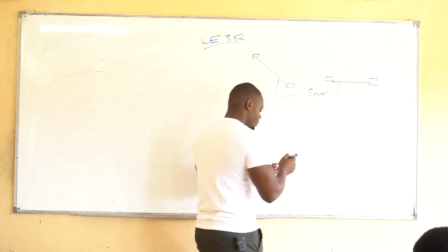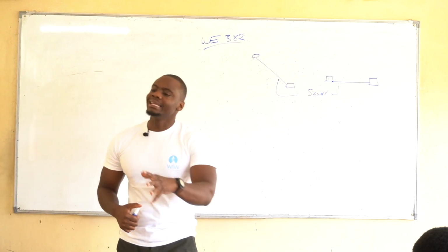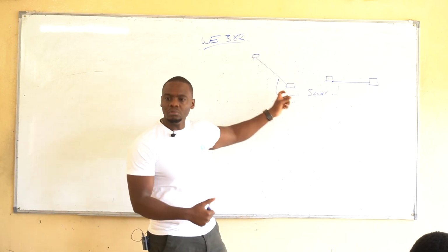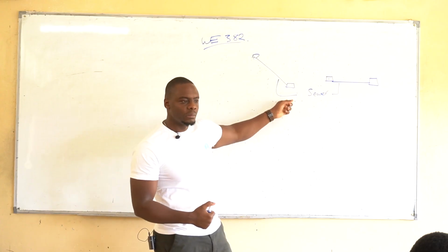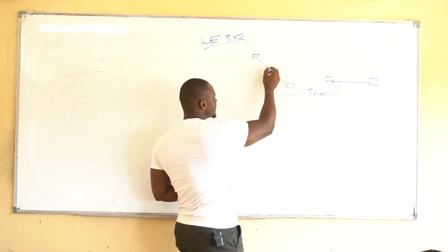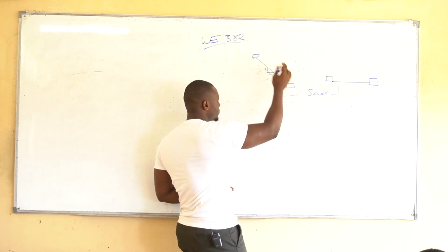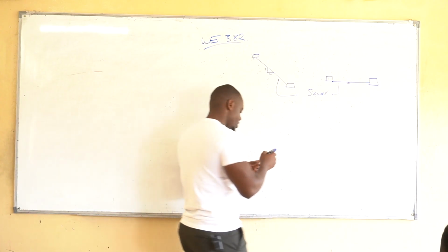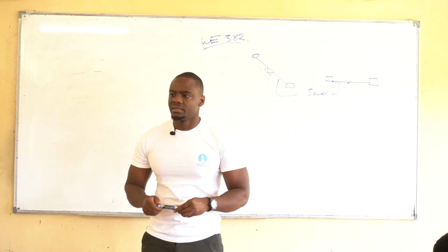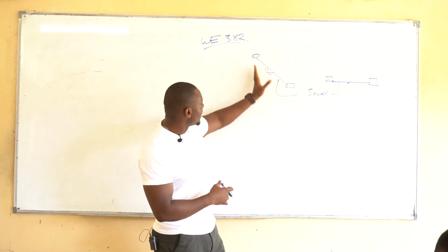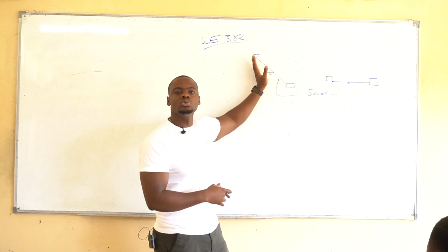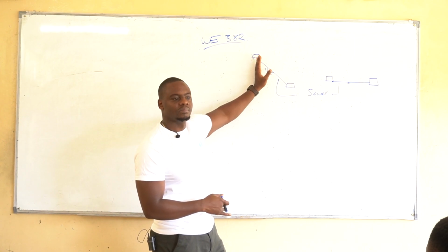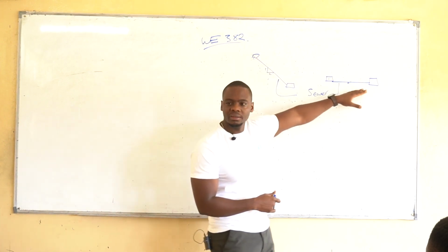And this is coming from what we call the self-cleansing velocity. There's the rate at which you want your fecal waste to move in that format. But then you cannot just guess the gradient. You have to calculate it. So we said if you just guess and then you make your sewer a little bit too steep, what will happen to your pipe? Okay, what will happen to your pipe here?